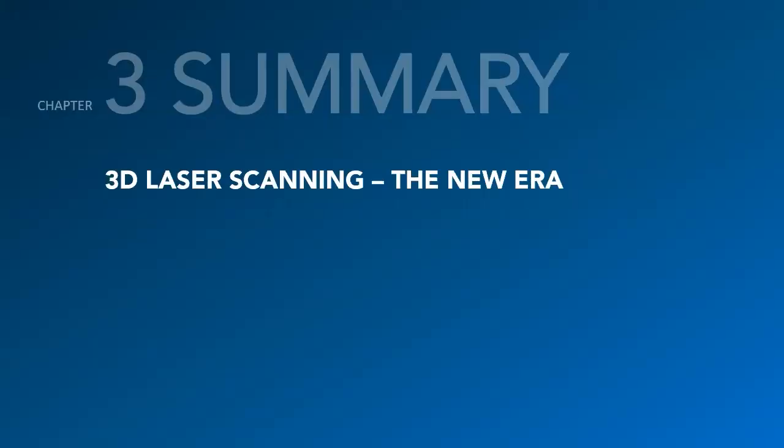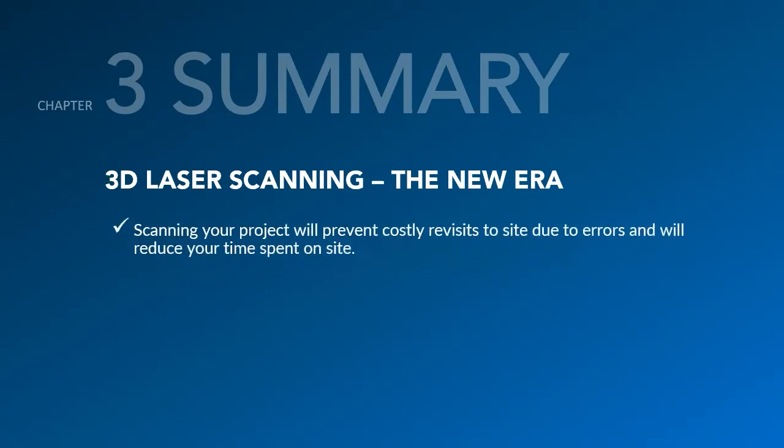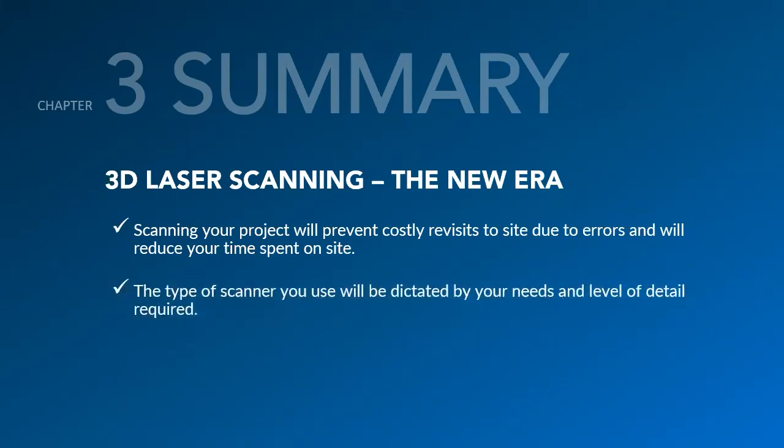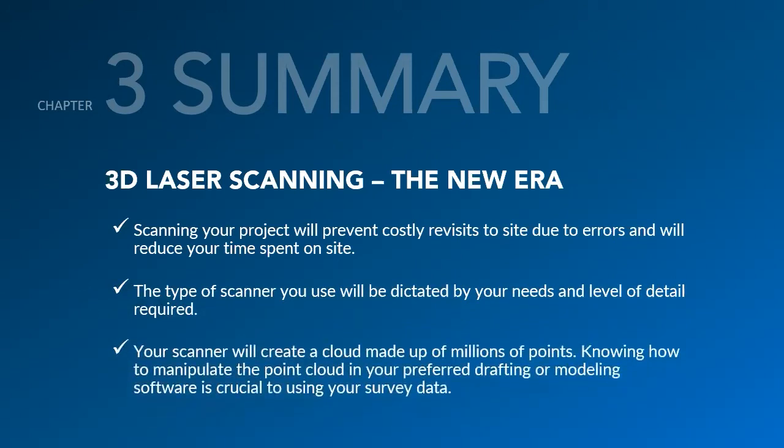So to sum things up, scanning your project will prevent costly revisits to site due to errors and will reduce your time spent on site. The type of scanner you use will be dictated by your needs and the level of detail required. And your scanner will create a cloud made of millions of points. Knowing how to manipulate the point cloud in your preferred drafting or modeling software is crucial to using your survey